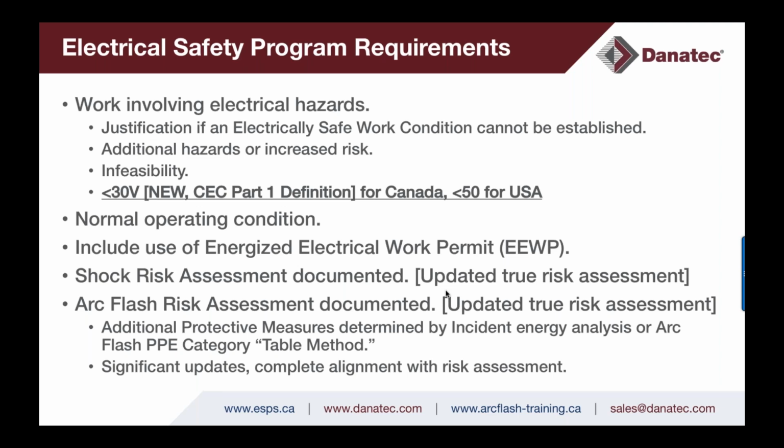One thing that I do work with clients is using an annual energized electrical work permit concept. So again, the electrical safety program, this is the real power for the owner of the electrical equipment or the host employer. The power of the electrical safety program is you can take the 70E and Z462 standards and you can embellish and expand upon their requirements to demonstrate implementation in the field in a practical and reasonable approach. So an annual energized electrical work permit, if you're interested in discussing that concept, get in touch with me and I'll explain it.